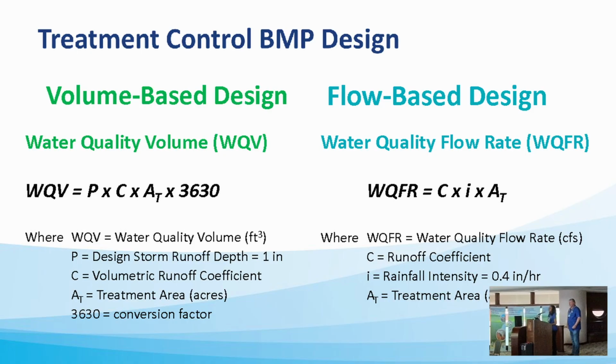And there may be site constraints, right? In terms of space, slope, lack of right-of-way, impact, structural foundations, environmental, cultural constraints. So it may not be possible for you to do LID or construction BMPs, or you may not be able to do them to the maximum extent practical. So you could maybe treat a portion of your site, but not all of it. So that is possible. So how do you know how much you have to treat, right?